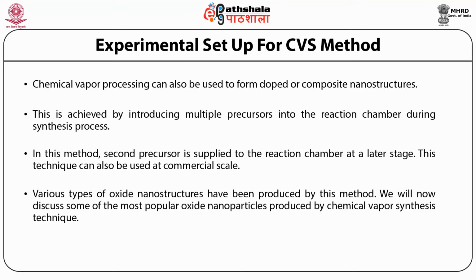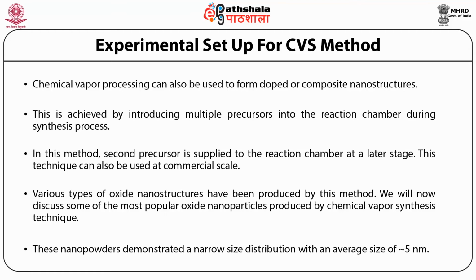We will now discuss some of the most popular oxide nanoparticles which are produced by the chemical vapor synthesis technique. Nano-sized particles of the oxides of indium, tin, and tin oxide doped indium oxide are synthesized by chemical vapor synthesis for their application in transparent conducting oxides, catalysts, as well as sensing devices. These nanopowders demonstrated a narrow size distribution with an average size of approximately 5 nanometers.